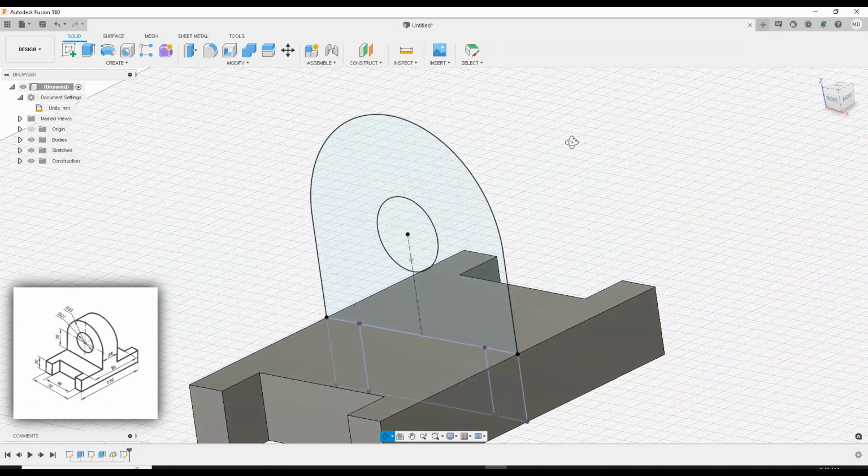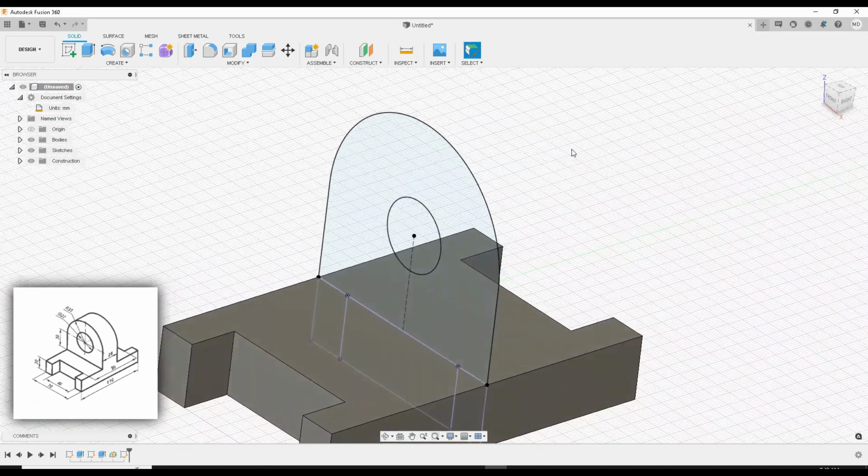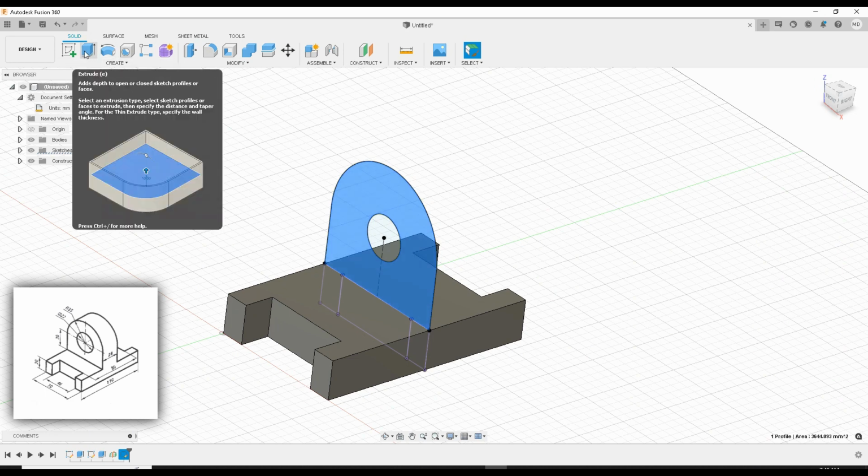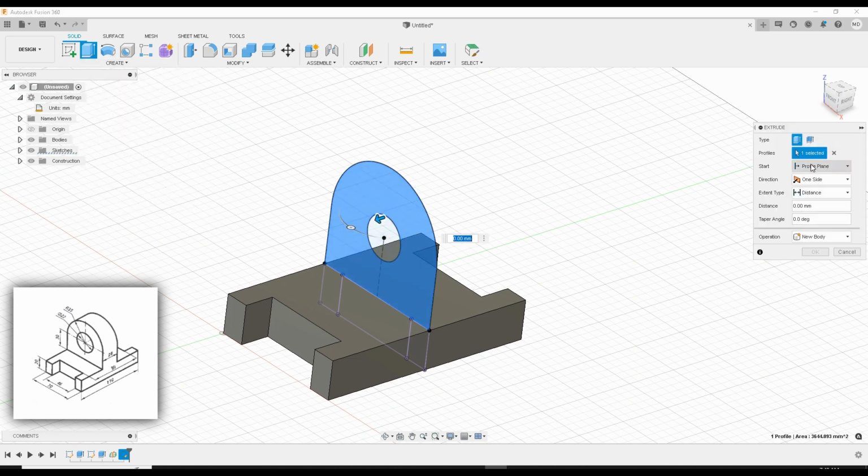Now when you go to orbit, it should sit right in the middle of the part, just like that. Okay, now we're going to use the extrusion and we'll be done. So click on the face, this profile, you see how it highlights blue, extrude, and a menu pops up, symmetric. Now we want to extrude in both directions. The dimension reads 28 millimeters.